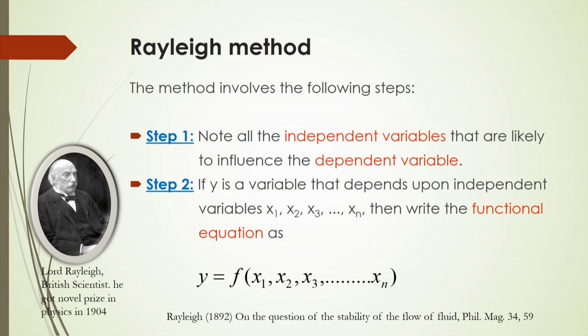Now, interestingly, this mass transfer coefficient will change with respect to the column diameter, flow rate of the gas, flow rate of the liquid, even the geometry of the column, and the physical properties of the system.